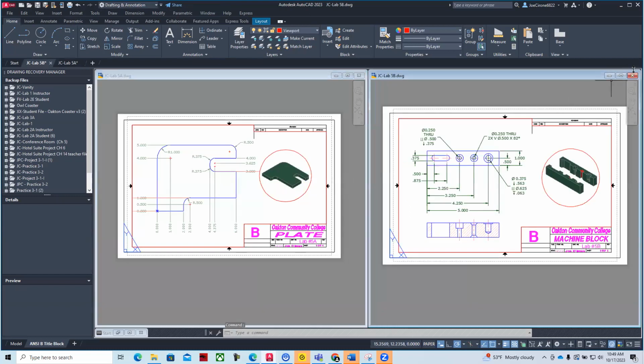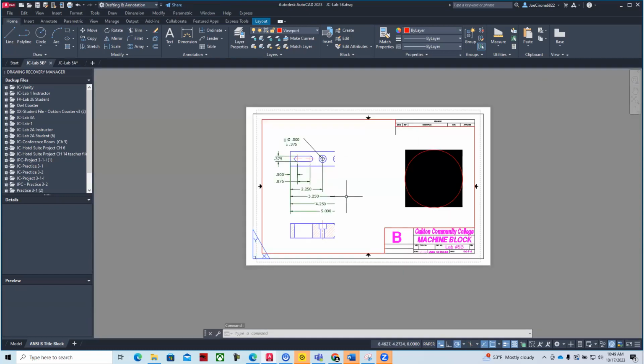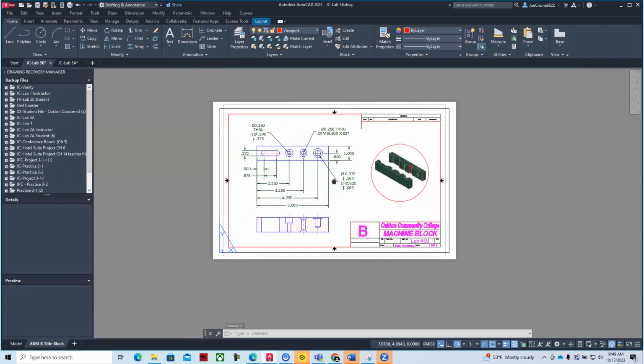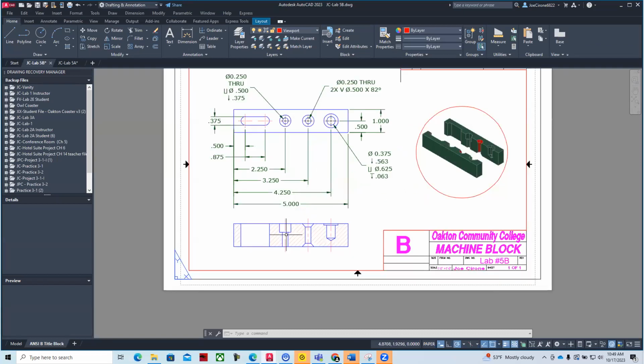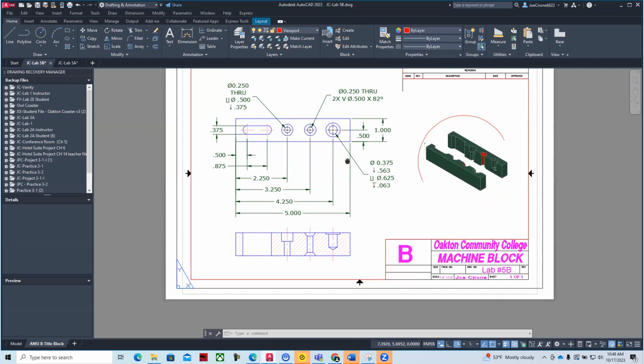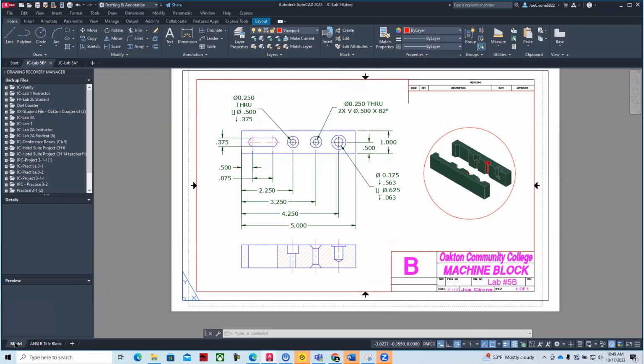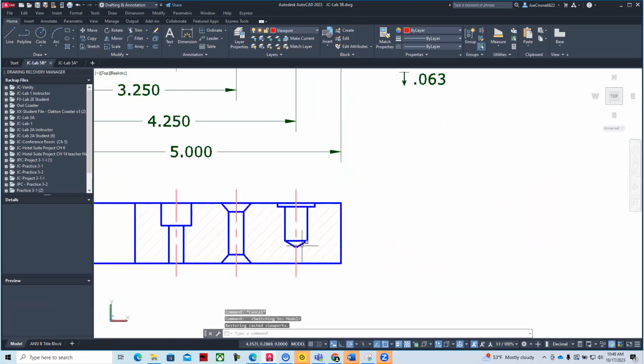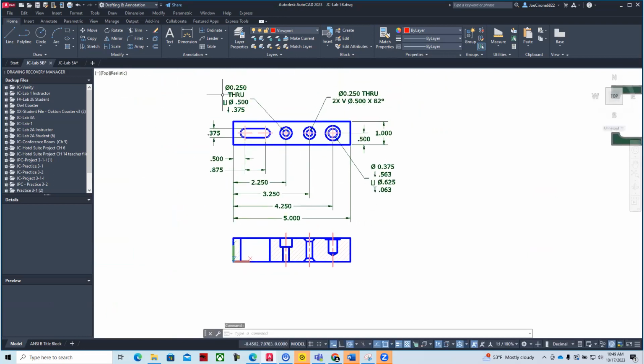And then the other drawing is a little bit more involved. As we take a look at this exercise, we'll be using the slicing tool, and we have videos for this. The idea is that we draw the front view and the top view, and then we dimension and annotate it. Some of the information, like the drill bit geometry and the counterboring geometry down here at the bottom, is in a PDF, and the textbook does a good job of it.